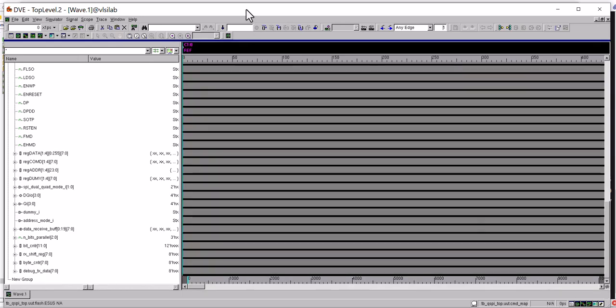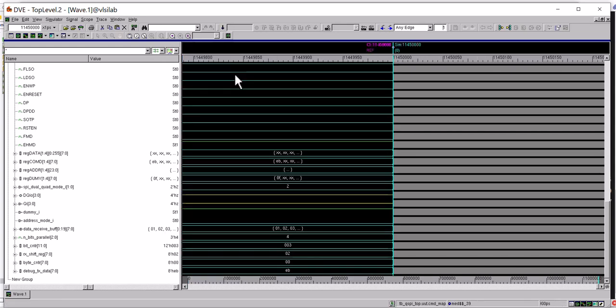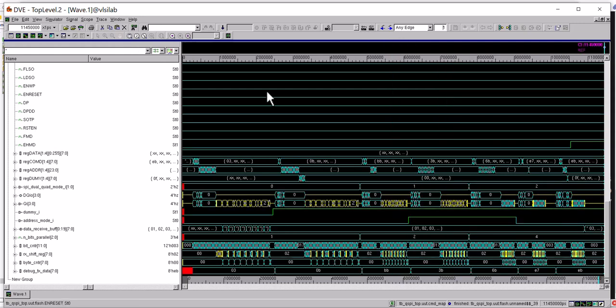So just hit F5. Obviously there will be the creation of the log file there, but for analysis we can go by the waveforms itself. So first is this debug TX data. It reflects what command we are sending, that is our 03, 0b, bb, 3b, 6b, e7, eb, like that.